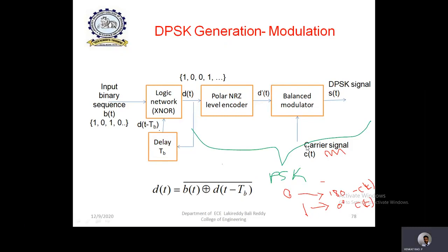For example, here in the modulation process, the carrier signal used has some sinusoidal waveform. It has some phase and frequency value. This same carrier must be used in the demodulation also, whenever we are using coherent detection. Coherent detection is nothing but multiplication of the modulated waveform or modulated signal with the coherent carrier. This is the simple representation of coherent detection.